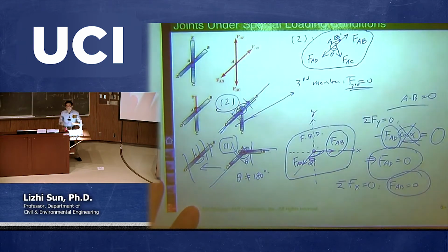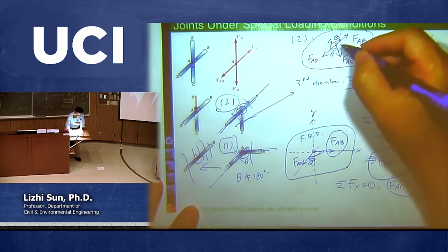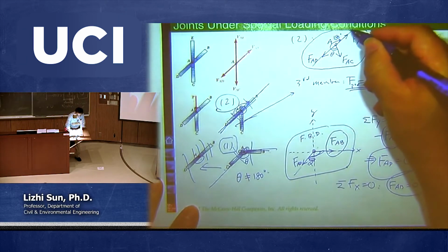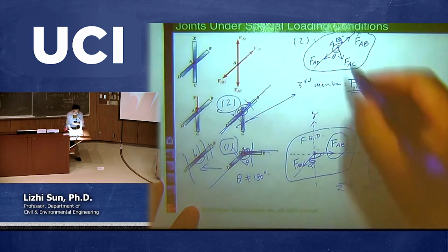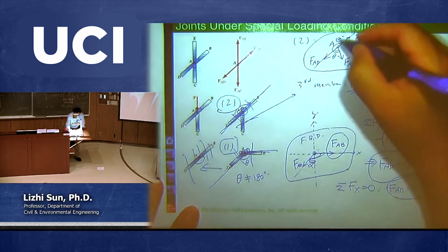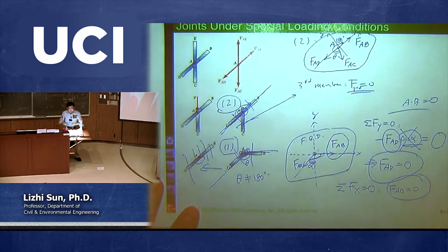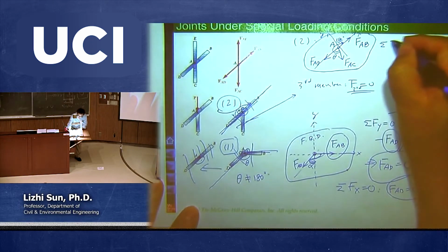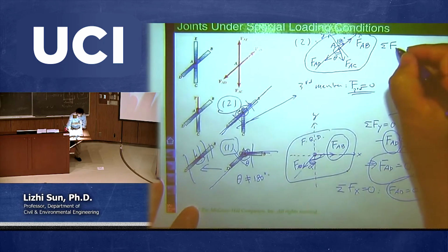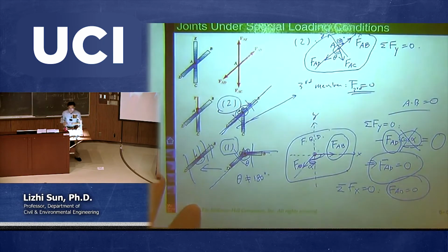we can establish, number 1, the coordinate system. I'm basically just calling this one the x direction. These 2 members in the same direction are called the x direction. And then the other one, perpendicular to x, is called y. Then again, I'm going to sum all the y components of forces in the y direction and set it to 0, because that's Newton's law again.